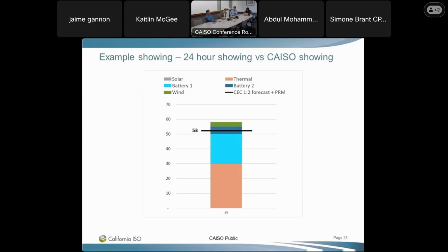The other question that I had is on the PRM piece. Just really quickly, and then I'll wrap it up, I promise. Thanks. Yeah, I know that we're going over here, so thank you for letting me get to this. But the point that was raised earlier that Christy was responding to about the PRMs and accounting rules and all these things for the solar piece is a bit concerning to me, and I think we do need to talk about it. I realize that the PRM is being discussed at the CPUC, but PRM is really a function of counting rules. And so if the CPUC sets the 2025 RA PRM at 17%, and then the CAISO is using 0.1 megawatts for solar, instead of the ELCC values for it in these validations, it's going to look like the CAISO is far shorter on capacity than what they were previously.